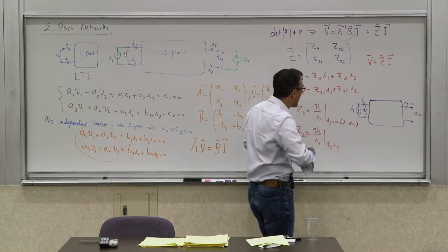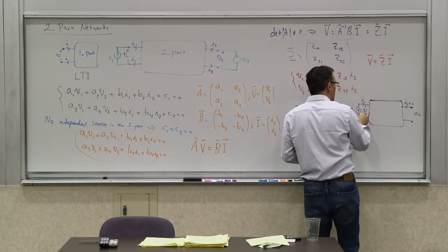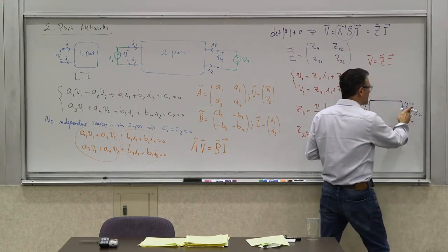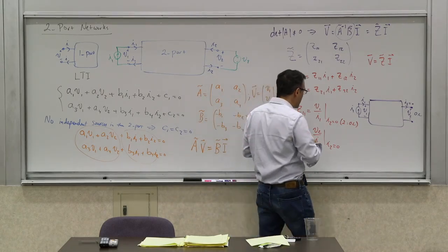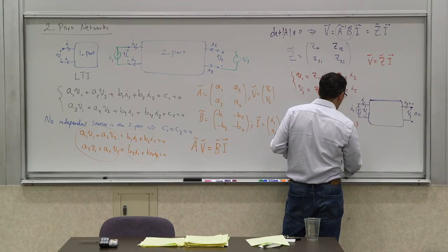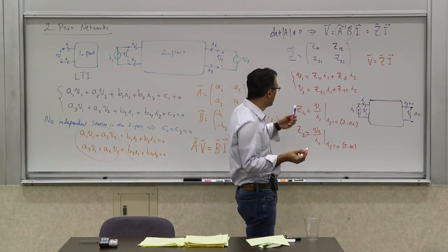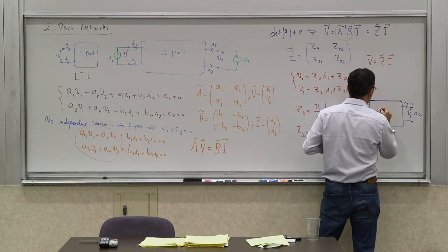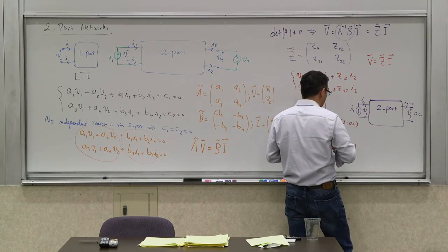It means that you apply an I1, but this time, instead of measuring V1 here, you measure V2 there, while port 2 is open circuited. You evaluate this ratio, and that would be your Z21. You can do similar things for the other two, and once you evaluate all four, you have characterized this two-port completely. So this is basically the two-port we are trying to characterize more accurately.